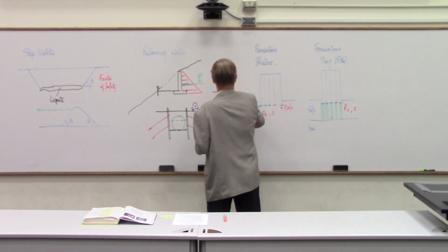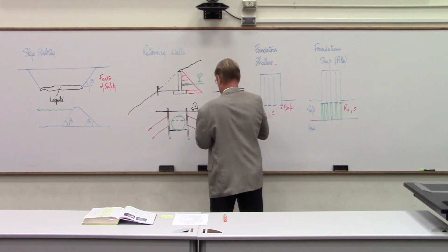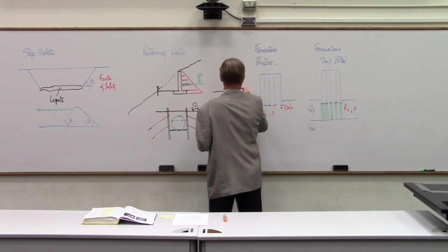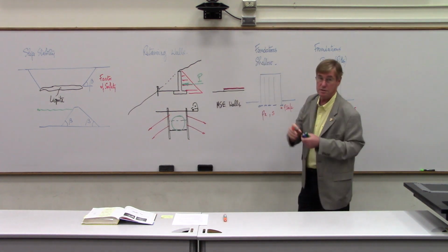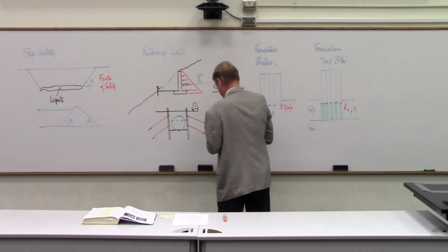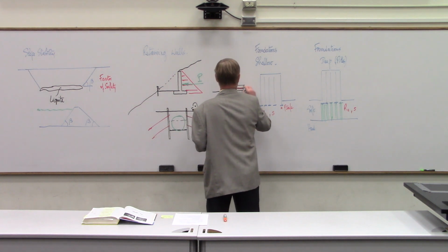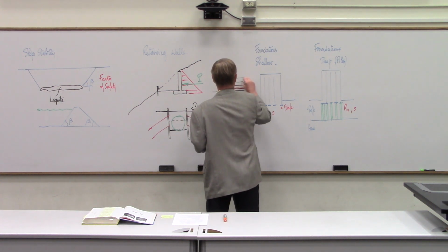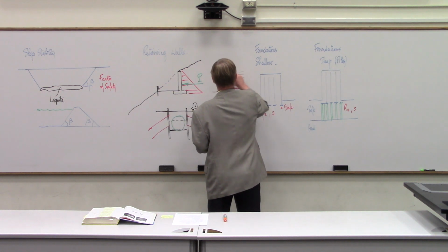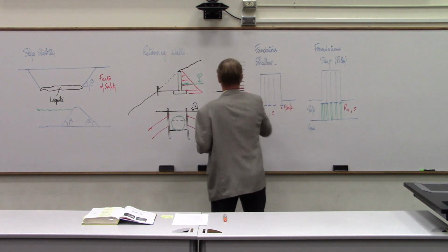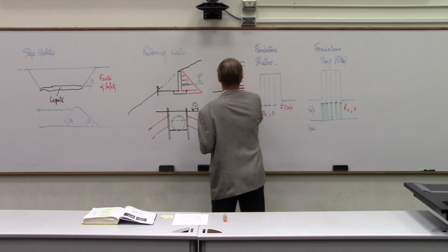The way these walls work is you place a layer of soil, and then on top of that layer of soil, you place a layer of reinforcement, steel, let's say. And then you place another layer of soil, and then reinforcement, soil, reinforcement, soil. And you can go up like this, 40, 50 meters. They're record heights. Okay? And then, as I said, you have reinforcement here at each level.